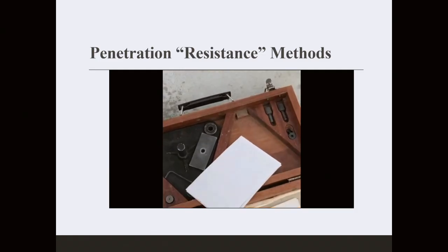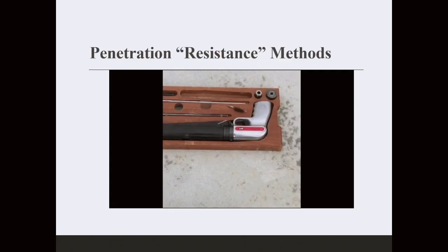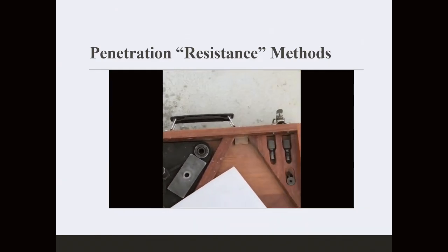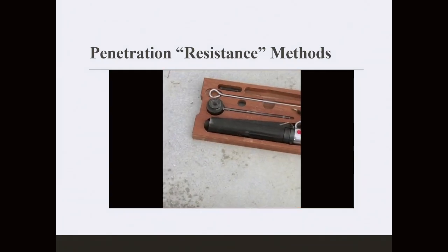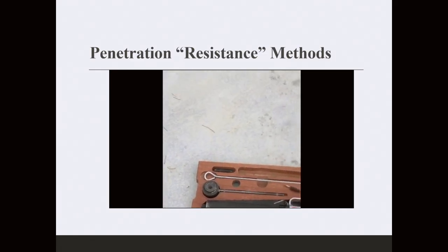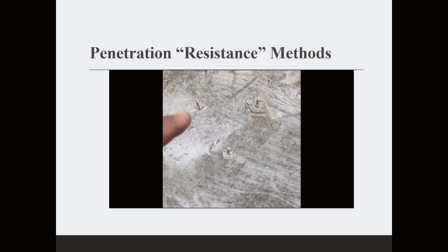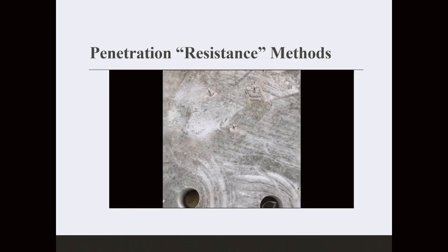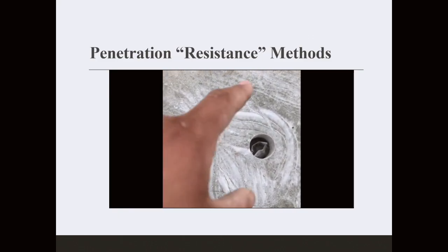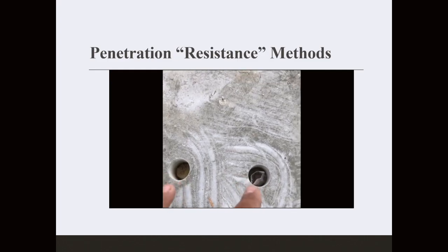The page he was showing was like 3,000, 4,000. These are compressive strengths at 28 days. In America, they go by pounds per square inch. So 4,000 PSI is 28 MPa. Usually 1,000 PSI is 7 MPa. So where he showed 3,000 plus or between 3 and 4,000, that means the strength is somewhere between 22, 23 and 28 MPa. So this is one way of doing business through penetration.